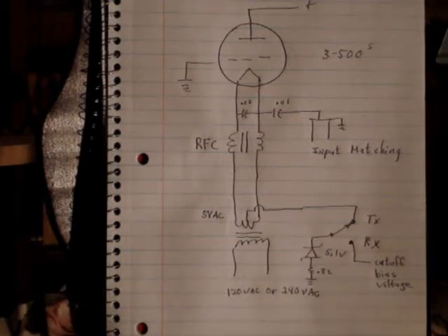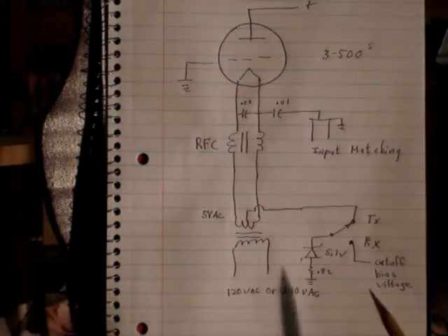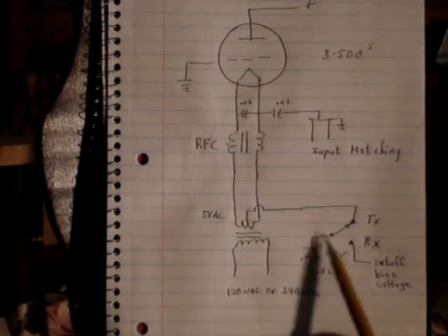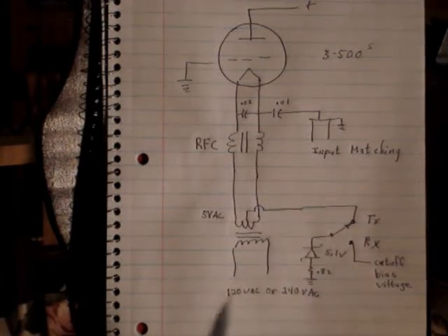Instead of keeping it always at 5.1 volts when there's no audio coming in, we want to raise that voltage up to some higher value, and the higher value will depend on what value we need to achieve our class A milliamps or current requirement.